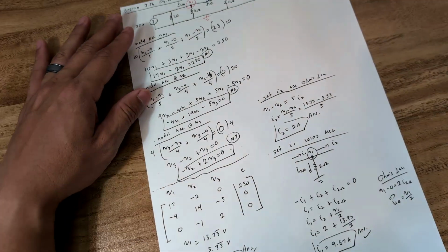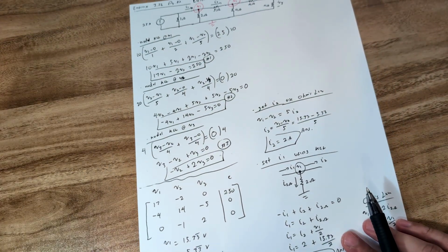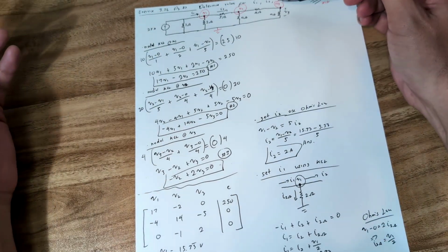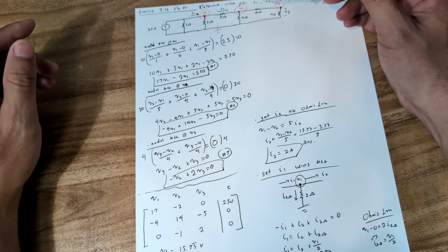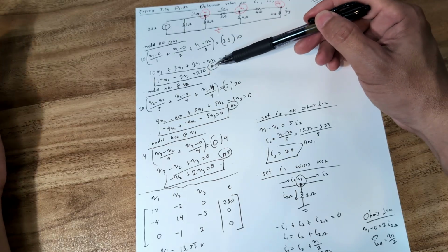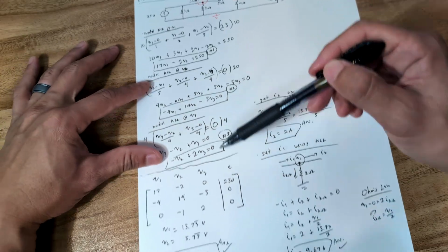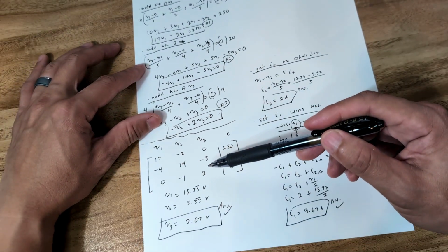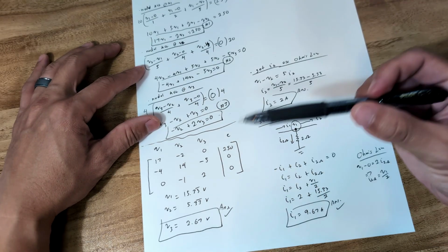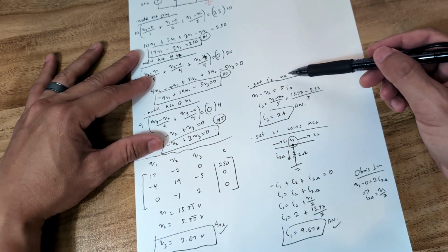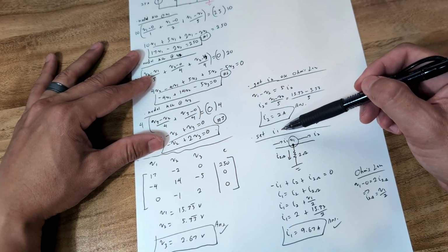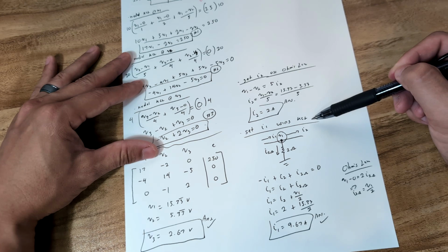So which one do I think is easier? Well, first let's walk through solving this part. For nodal analysis, you had to define V1, V2, and V3, and solve for V1, V2, and V3 using nodal analysis. So we got our equation 1, 2, and 3, and then we plug that into our augmented matrix using our calculator. We solved for V1, V2, and V3, which gave us one of our answers. But then you had to go another step to get to I2 using Ohm's law, and then you got 2 amps for I2. But then you had to get I1 using KCL and Ohm's law.